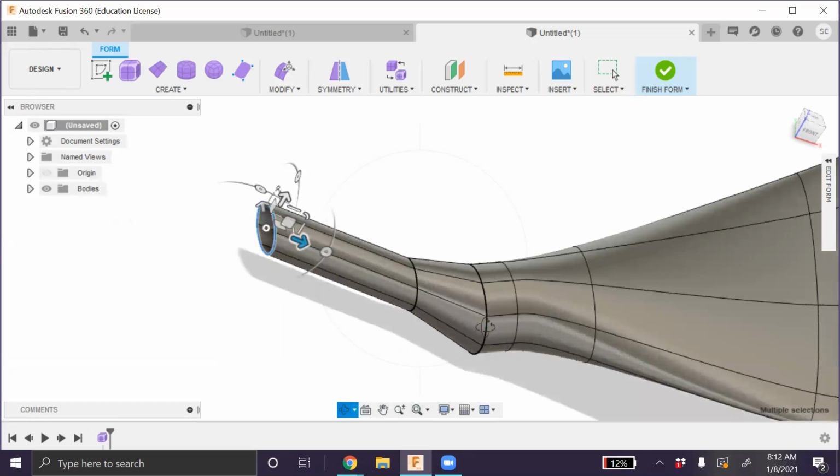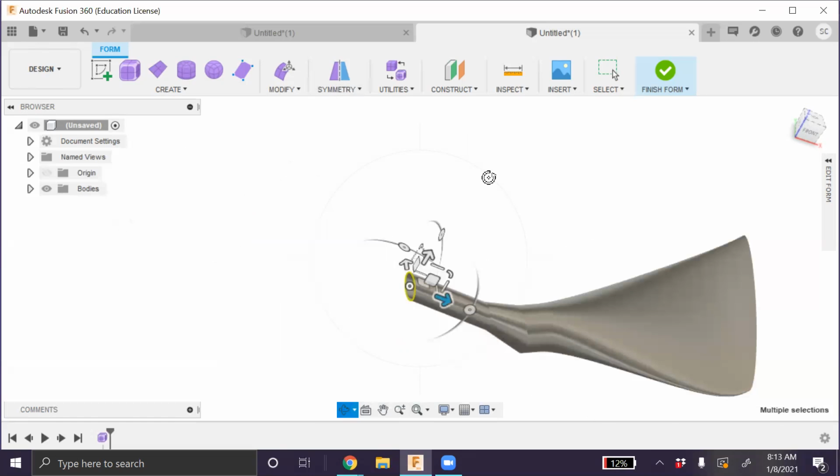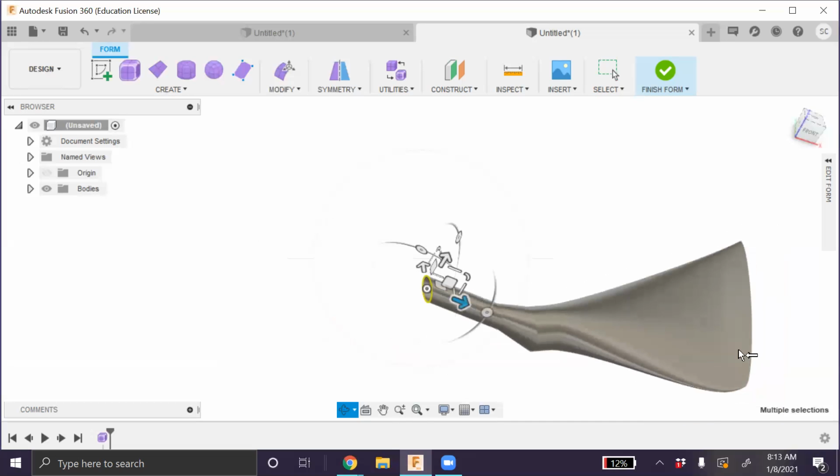This blip that you see over here is because while I was moving this, at some point of time, I have used one of these arrows to slightly shift it out of posture. That's why this blip. If you just held this straight and pull it along with Alt Control and drag, this blip wouldn't have happened. So this was about the basic commands and interesting shortcuts in Fusion 360's freeform modeling.